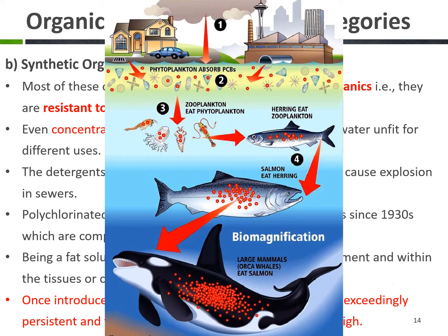Hopefully, you will understand. And you might have gone through the sag curve. The sag curve is about the disposal of organic content into a drain or water body. If you note the DO level at the moment when the effluent is added into the water body, and then gradually follow the concentration after that, the DO level will reduce significantly, and then it will rise again. So this develops a sag curve, and this sag curve indicates how much treatment is required within that water body.